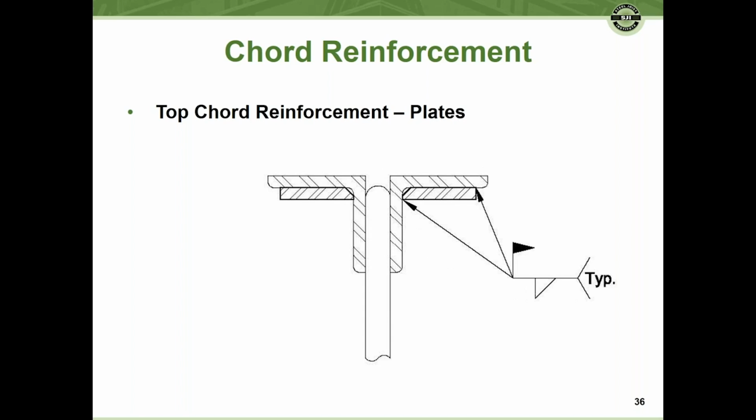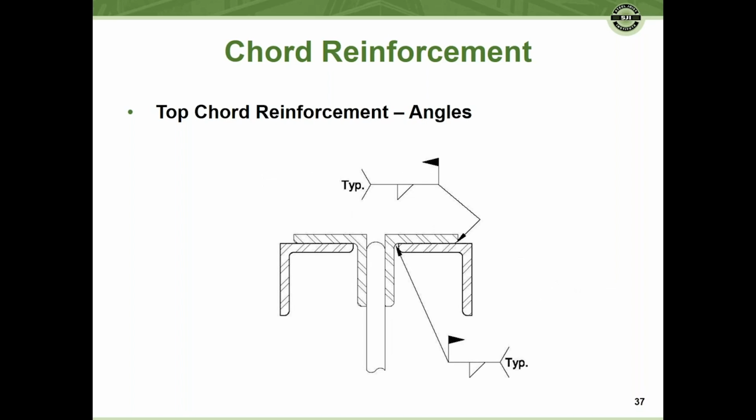In this case, we're calling out some overhead welds, and we can't put plates on top of the joist because we're assuming that there is some deck on top of the joist. And that's going to eliminate that opportunity without removing the deck, which is kind of a big deal.